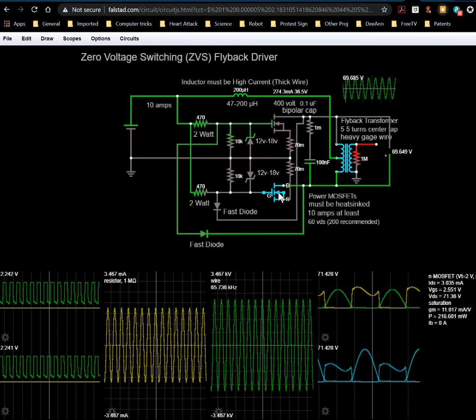So basically, it keeps it off at a very low current the whole time. If you actually look at the voltage, you'll find out it's not zero. This voltage is never zero across this transistor. You can see all the parameters of the transistor when I highlight it: gate VGS, VDS, etc. But at any rate, it's never at zero. The point is, this is effectively turned off when this is turned on, and vice versa.